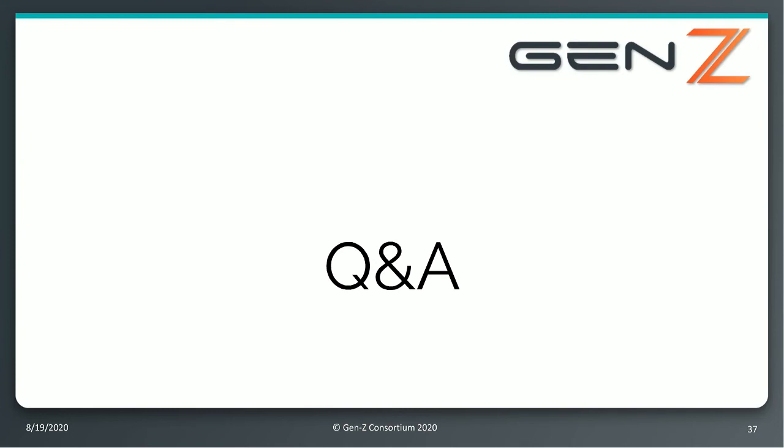Great. And then there was a question that came up, I believe, in the last few slides that you were presenting, that stated, so what happens when you go to PAM4 with the losses? Was that tested? So this is Ralph. I could answer that. Yeah, we obviously tested it with PAM4, as you could see there. One thing to note when I was showing you those, where we got a couple of errors on 2 of the 4 channels, none of the channels were optimized in any way.